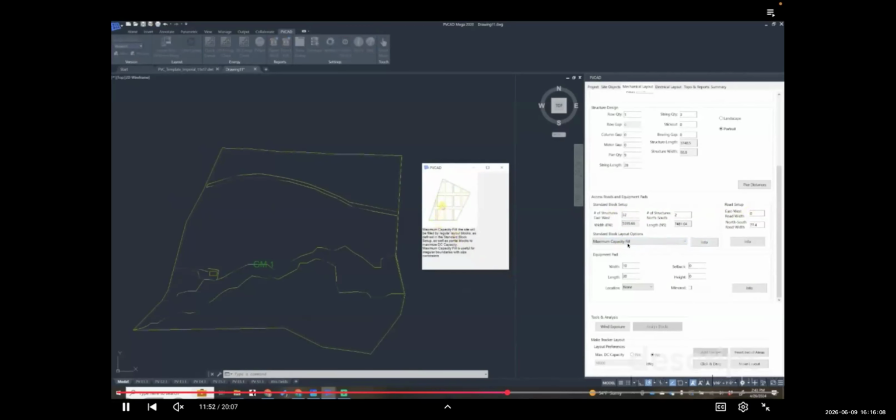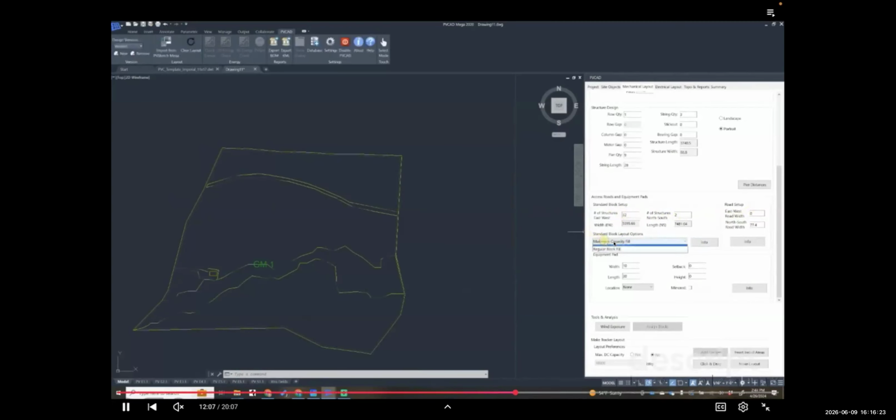So what I'm using right now is a max capacity fill. So it'll take the full blocks, also the partial blocks, wherever it could fit. You can switch from that to, let's say, a regular fill, right? And that would only take a complete full box or a full block, and exclude everything which is a partial block in the design. So let's look at an example of that.